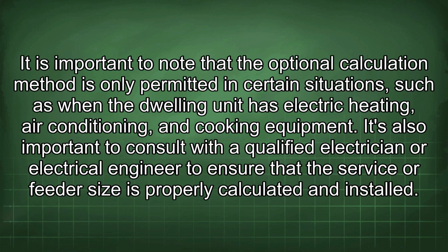It is important to note that the optional calculation method is only permitted in certain situations, such as when the dwelling unit has electric heating, air conditioning, and cooking equipment. It's also important to consult with a qualified electrician or electrical engineer to ensure that the service or feeder size is properly calculated and installed.